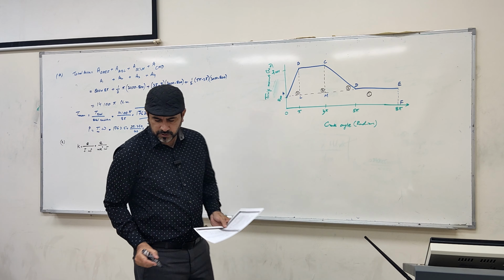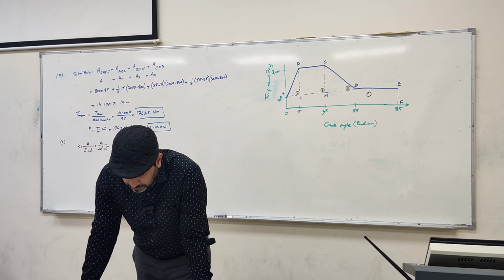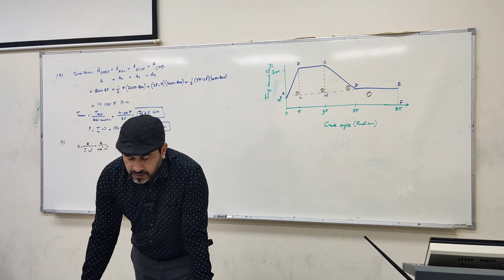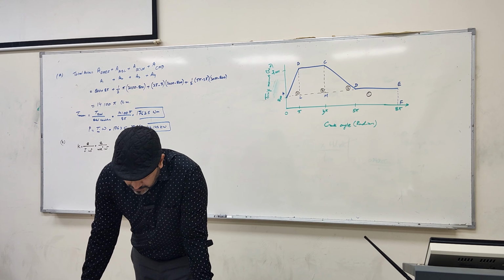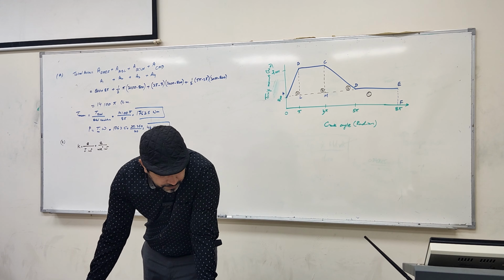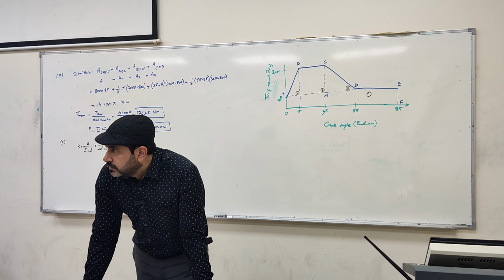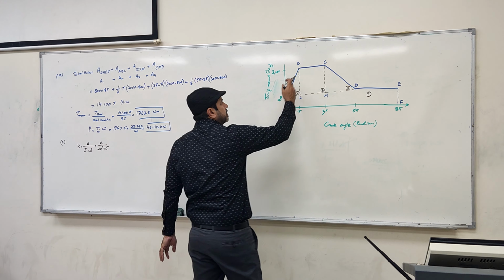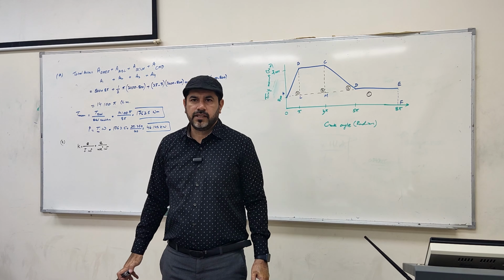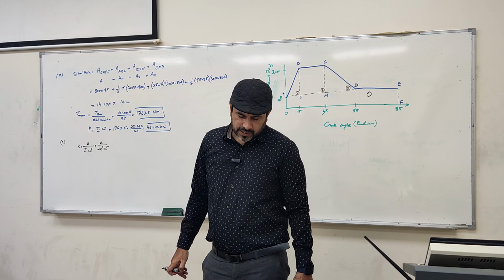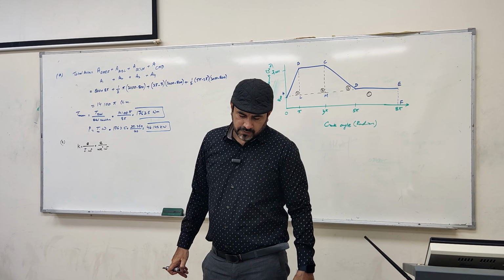What is the E? Small e. Maximum fluctuation of the energy. What is that maximum fluctuation of the energy in the graph? It is basically the amount of energy or torque above the mean torque. So we need to find the torque above the mean torque. So we'll draw the torque, revise this area under the curve thing again, and we will be able to find out the value of E. Then mass is given, K is given, omega is given, all we put into it.